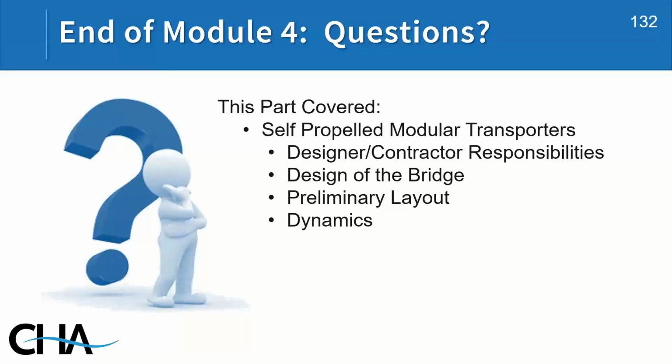The best way to describe an SPMT is a fluid system, a fluid suspension with hydraulic fluid that flows between zones, and they can configure the SPMTs to have different zones. So they typically go for 3 zones, like a tripod, to make sure that they have a stable system. The SPMTs are linked together to do this in some cases. And that's all under the contractor's responsibility to make sure the stability is maintained. We'll cover that in a later module.